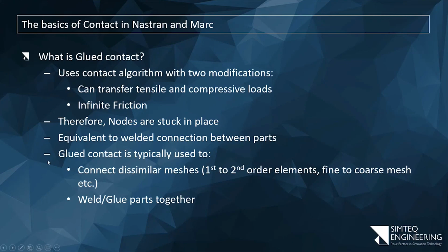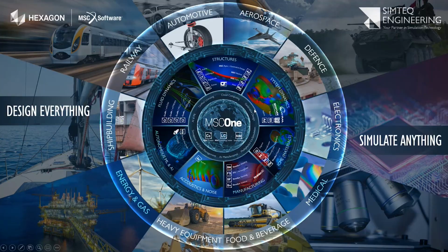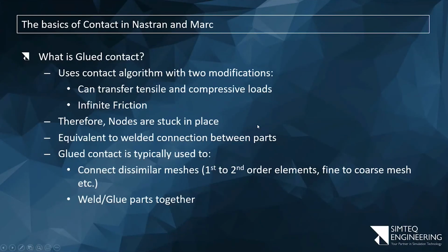So in this case, we start with an infinite friction or infinite stiffness sideways between the two parts, and we transition to a force, and there's some discontinuity in between as well. So that's the stick-slip method. At some point, we'll spend a bit more time on friction models, the pros and cons, the reason they exist, and so on. But okay, that's what I wanted to discuss for today.